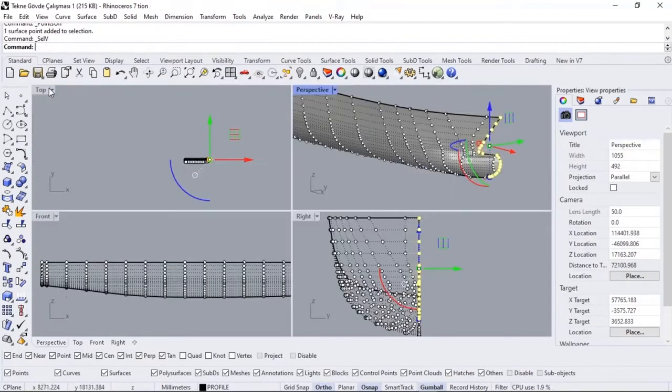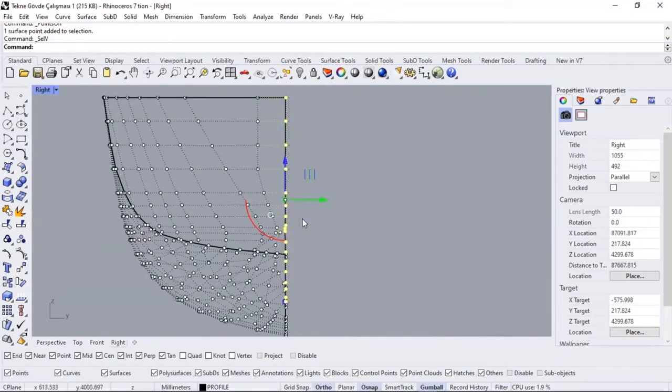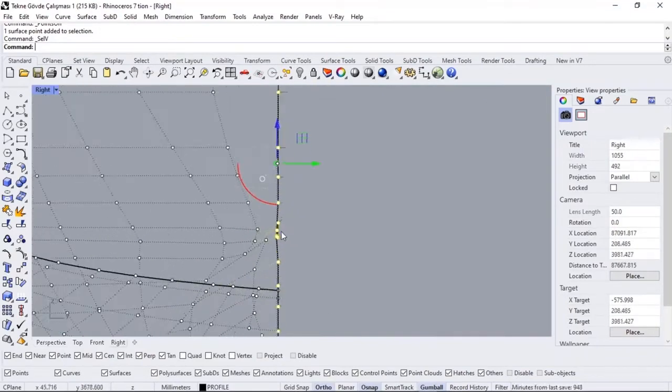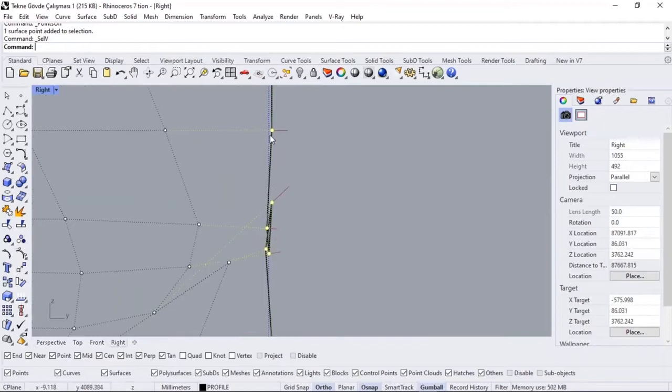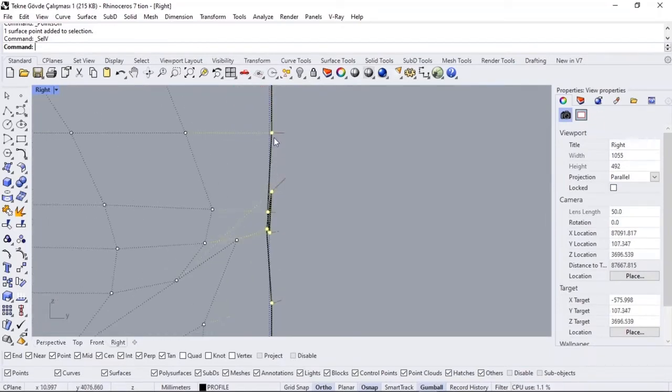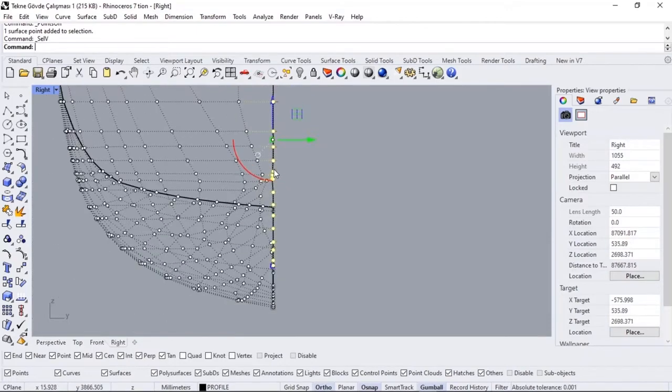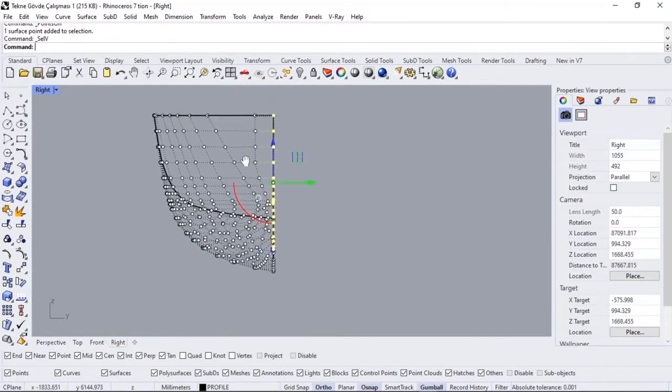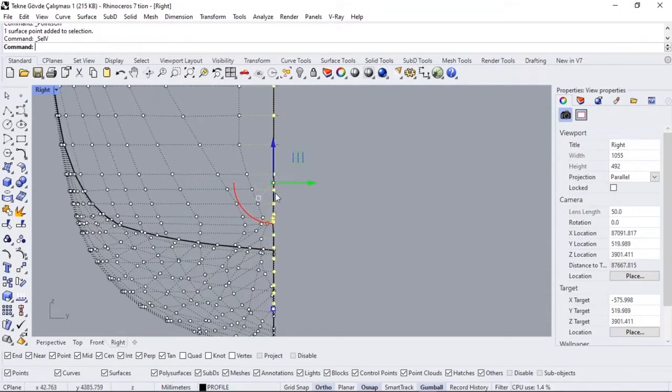Then I get help from the two-dimensional view. I click Right view. As I approach the control points, I will see that they are not all on the zero line. We need to keep all of the control points here at the zero level. If you don't, half the surface is on the screen right now. When we reflect the other half of the side, the middle will be empty. Therefore, the control points here must be exactly at the 0 point.